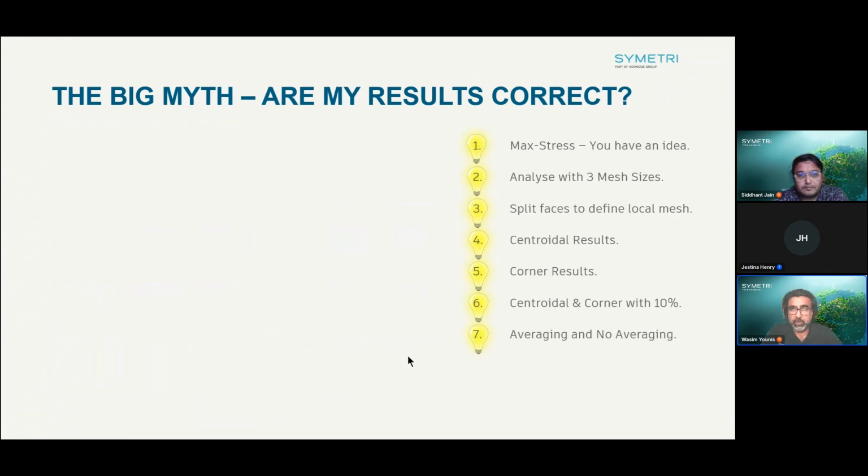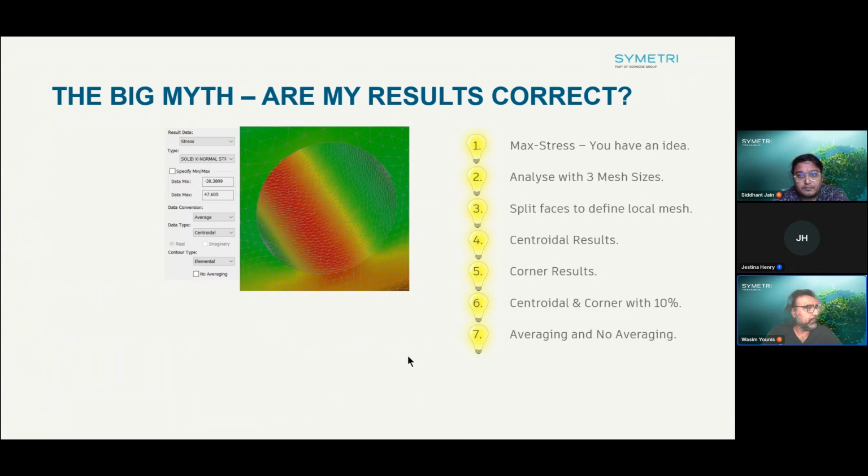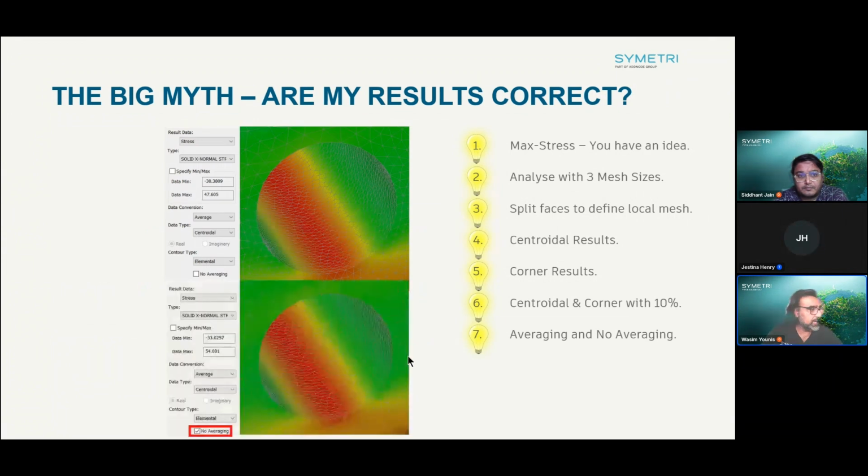And this one, I think I use this a lot. When you have a very fine mesh, everyone, then by simply clicking on averaging and no averaging is a good way to check that you have also received convergence. If the 2 plots don't look anything similar, then it basically tells you that you have to go and refine the mesh. So these are extra tools and tips for you to have some sort of more confidence in your results. So this works fine